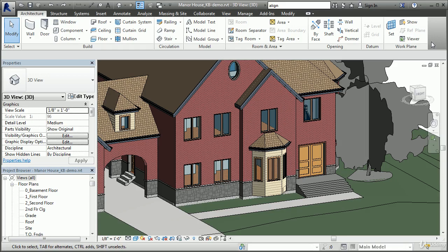The information in building information modeling refers to all of the input that goes into the building design, including things like materials, wall construction, the number and type of doors and windows, floor areas and usage patterns, energy analysis, quantity takeoffs, and even cost estimates. All of this information is contained in an intelligent three-dimensional model of the building that can be viewed in a variety of ways and outputted to fully coordinated construction documents.